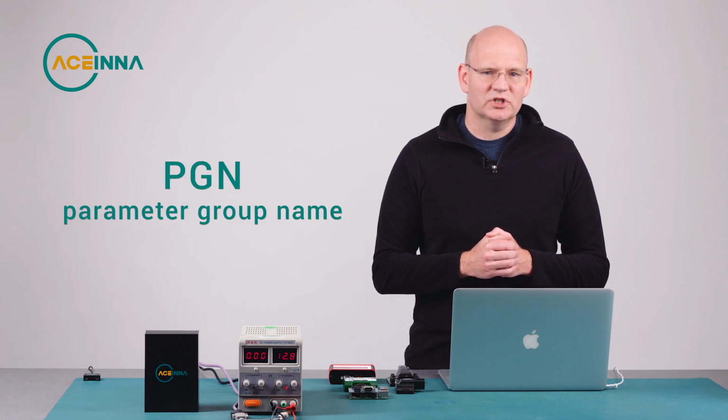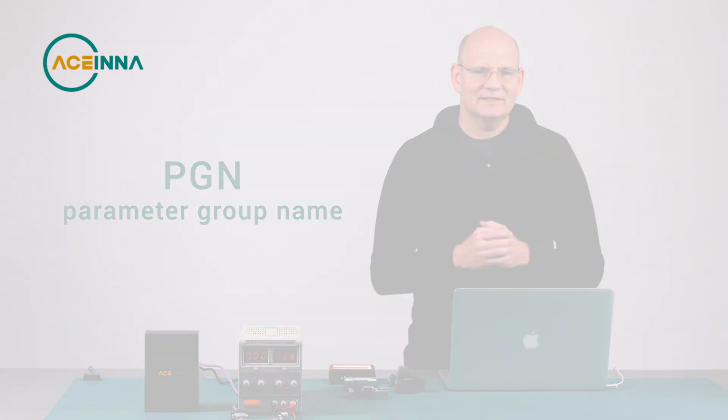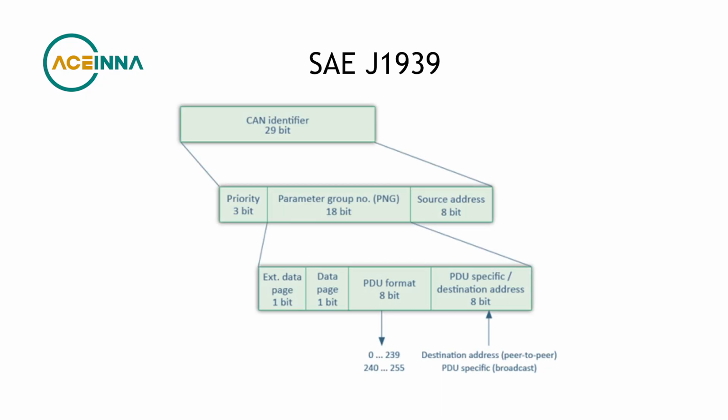J1939 defines messages with a PGN, or parameter group number. Inside the messages are datums. These datums are defined by slots. Slots give the encoding of the datums. PGNs and slots for roll, pitch, acceleration, angular rate are shown here.